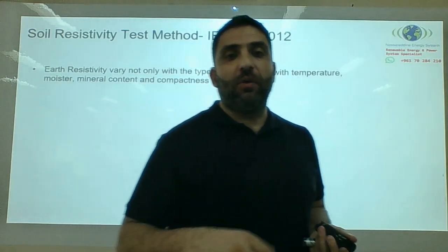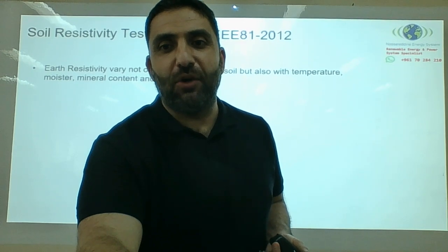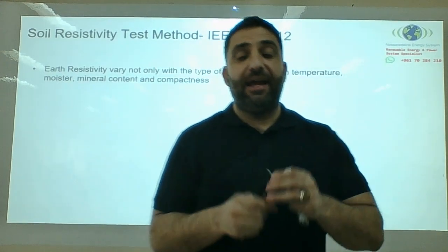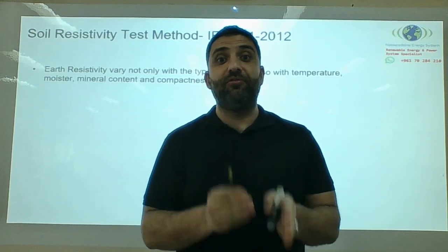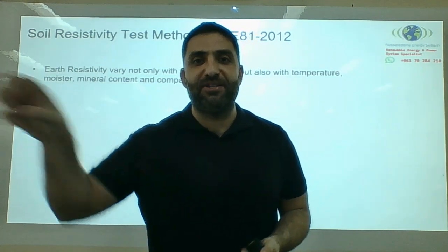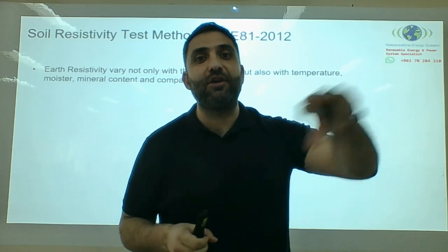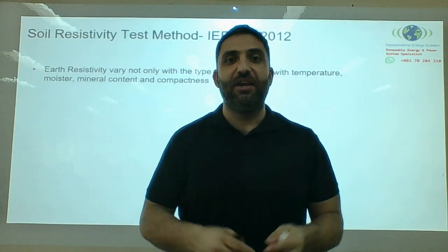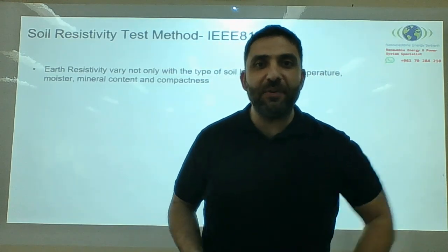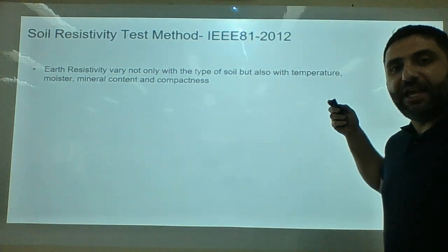So whenever I go ahead and measure a soil resistivity, it's very important for me to note the type of soil I measured and also the condition I measured under. Was it wet condition? Was it dry condition? Humid? All this information, as you will see, plays an important role.